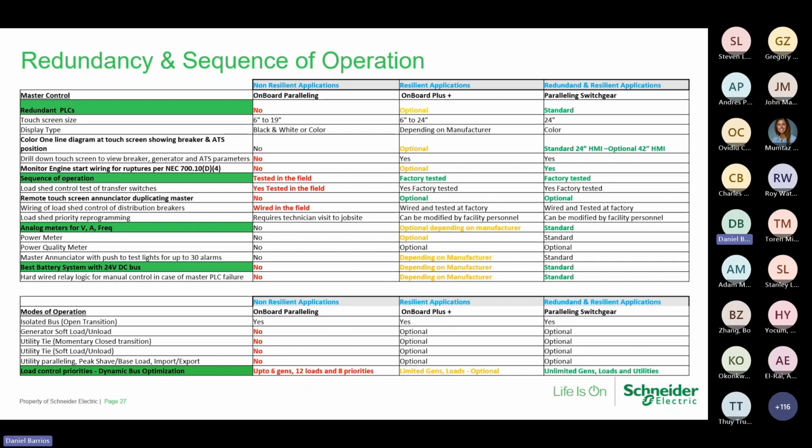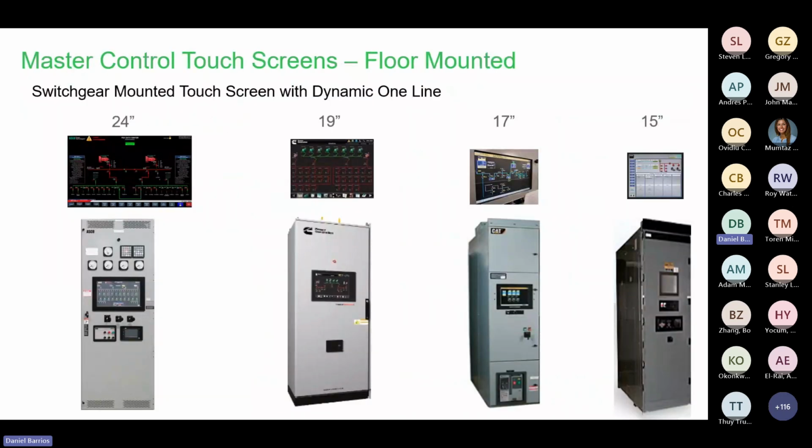Hardwire backup logic. We're going to stress that to you in order that if you have lost your controls, if you have hardwire backup from each of your individual transfer switches, should you have even lost some of your advanced controls, that will still send the start signal, and at least your priority one loads will be put online by a hardwire backup scheme. And each of the others you can go through. We would like to discuss these with you after you've digested these questions and points and bring them to our attention or such.